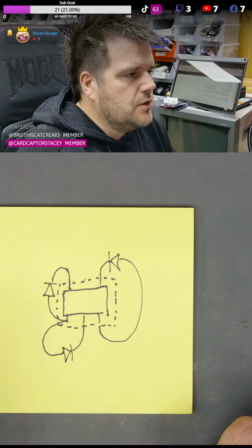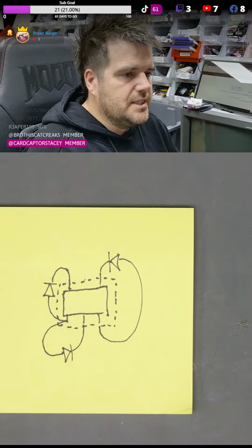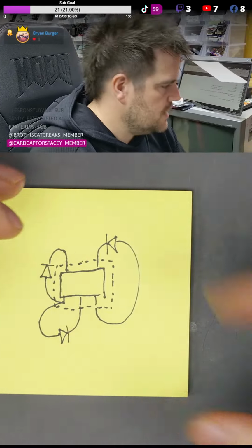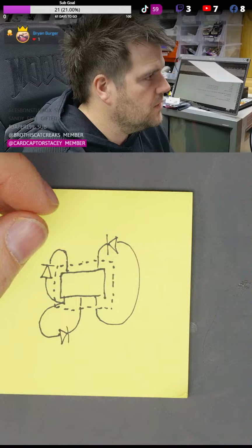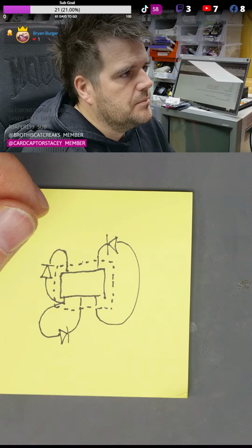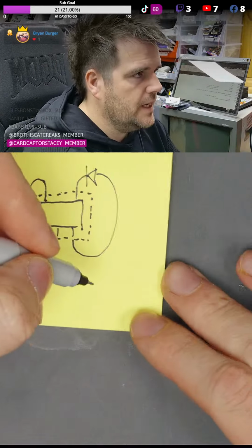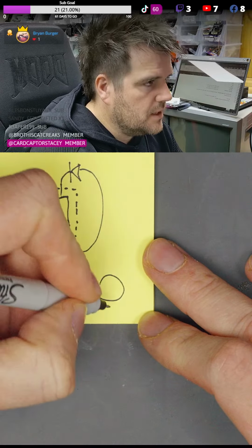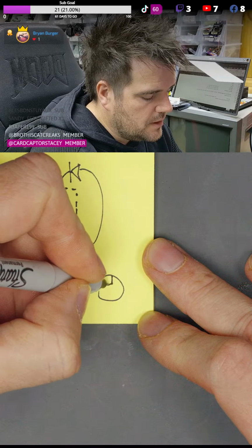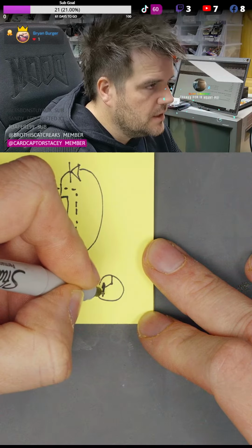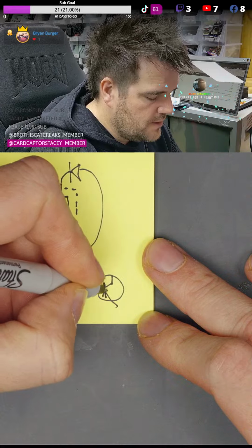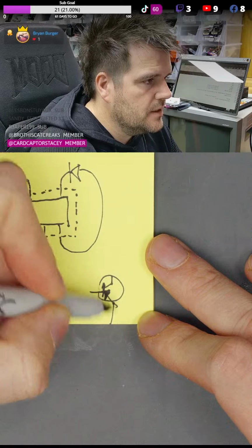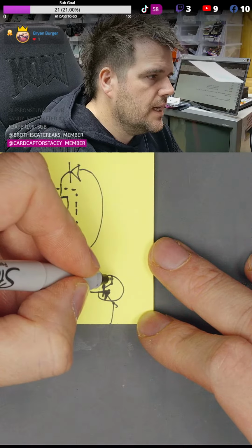It wouldn't be a Q though, because if it was diodes it'd be a D. So it's going to be a transistor package. And then obviously transistors have diodes on the body. So when you see, say, a transistor package, which would be a classic circle, you go down into your base and then you come out here. So you're either going to have an arrow pointing in and coming out. And this is your diode here. You can have body diodes as well.